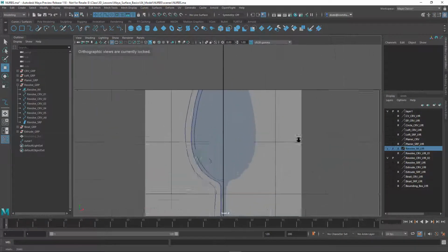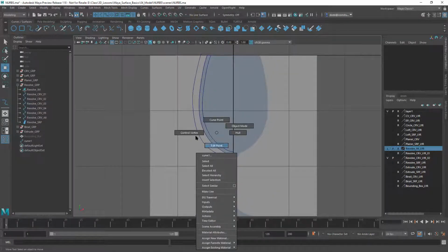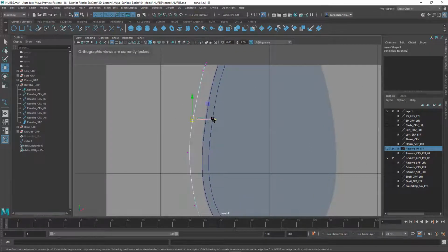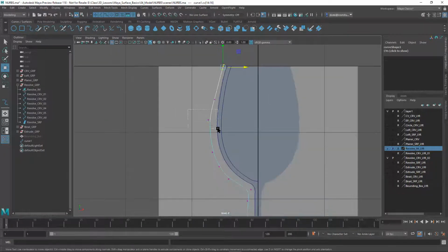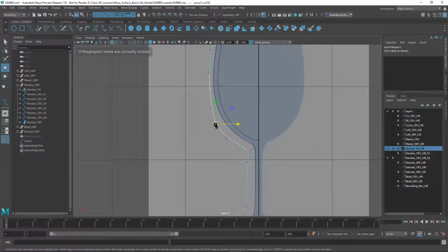Yeah. Okay. So this would be an example of using curves with image planes. So let me go back here, do control vertex. Now you can see. Okay. So I've shown that before, but now you see an instance where that is very useful. So basically you would just go in here, and if you work with any kind of 2D graphics program where you're used to working with splines, you'll find working with curves in Maya really nice.